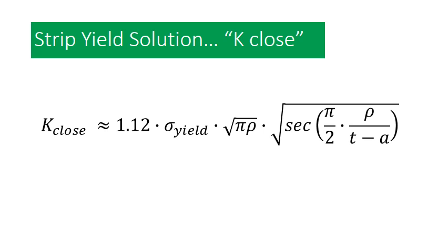And then we've got square root of pi times the plastic zone depth, and then we have a secant term as well. The secant term also represents the back wall correction factor, but in this case, we're not looking at the full wall thickness. We're looking at the wall thickness minus the crack depth, and we're doing that in terms of the plastic zone depth.